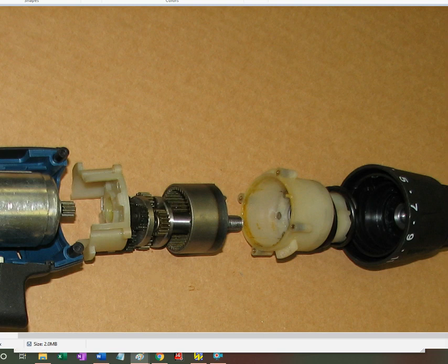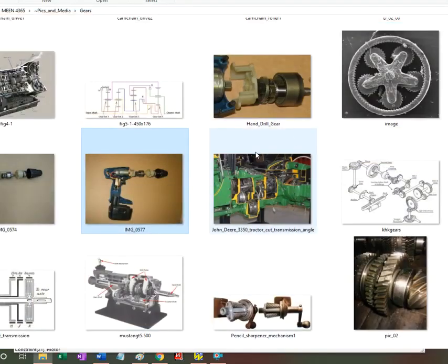So this would be the sun gear of the first unit. The carrier of the first unit is part of the sun gear of the second unit. They both have ring gears that are identical, which helps reduce the inventory or number of different parts for the assembly. So you have the first unit and its ring gear and an identical ring gear, and they're fixed to the ground. Okay. Anything else?